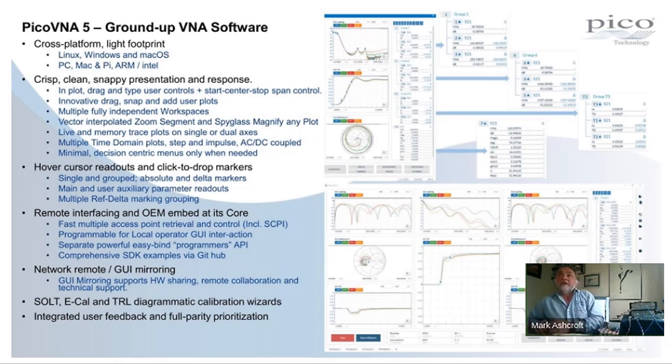Most importantly, this software has been designed for the automating programmer and for the OEM embed opportunities that we see for the VNA. There are two remote programming interfaces. One is a traditional SCPI interface for the GUI, the graphical user interface. Here you would control the VNA through its graphical user interface.